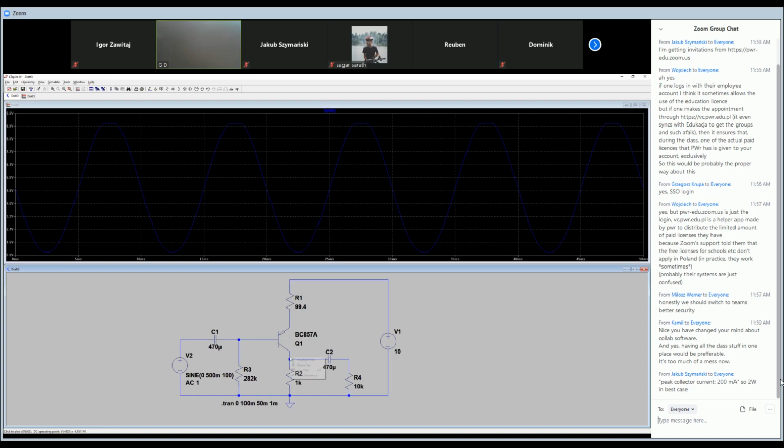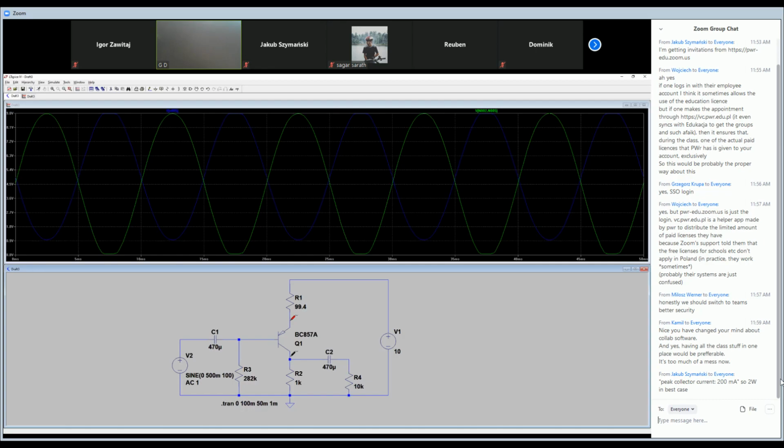It means that when I use the mark here, for this point, as you see, the voltage between the emitter and the collector is going to this value. It is almost zero. Last time I told you that the saturation voltage for the transistor is around 0.2 volts. Let's check how many it is.